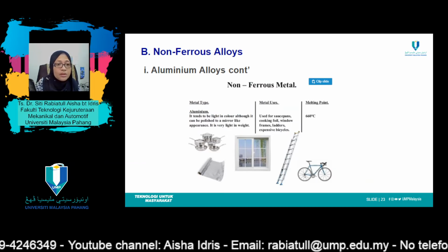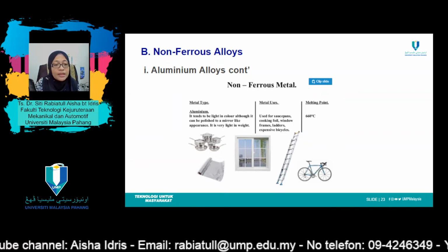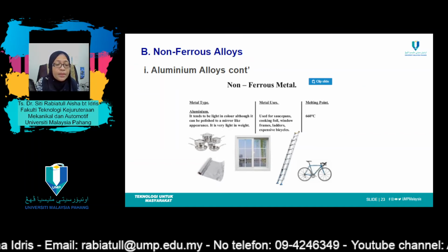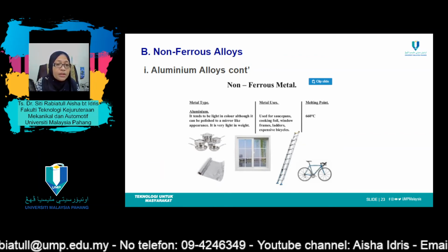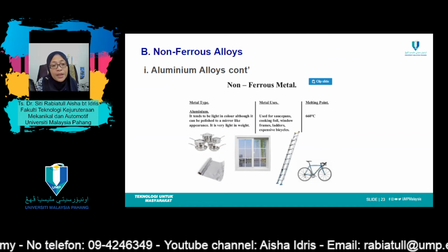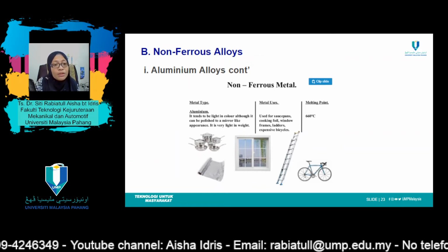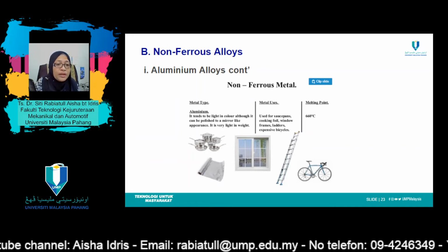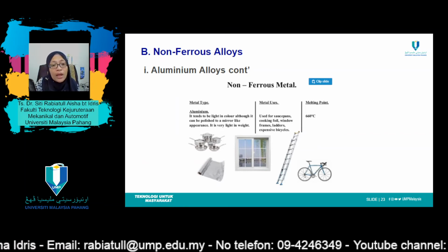Generally, aluminum alloys are classified as either cast or wrought. Composition for both types is designated by 4-digit numbers that indicate the principal impurities and in some cases the purity level. For cast alloys, a decimal point is located between the last 2 digits. After these digits is a hyphen, and the basic temper designation is a letter and possibly a 1 to 3 digit number, which indicates the mechanical or heat treatment to which the alloy has been subjected.